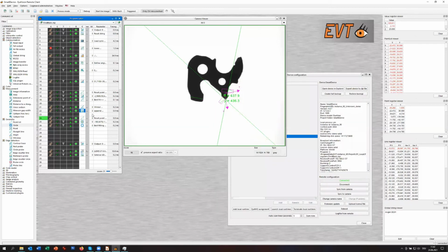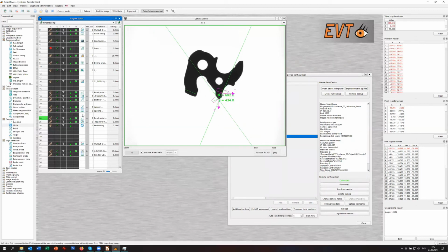And let's run it again. If you have a look at the bottom, the global string viewer, if you run it again to this position, now we see "angle:" and 12082, which simply gives you an overview of what we send out over the UDP package, or what is transferred when we arrive at this point.